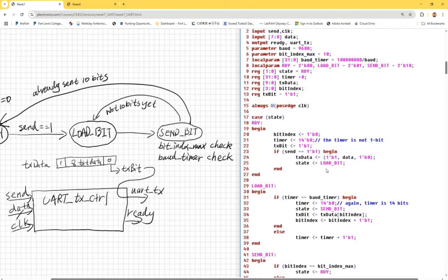So it's not generating a parity bit. You can modify it to generate the parity bit. I think the sender makes a decision if the sender wants to send the parity bit or not. Right? The checker, the receiver, will be able to receive it and eventually do the XOR and generate that parity and see if that works. So it's given that the receiver already knows the system is using even parity checking or odd parity checking. It has to know it first.